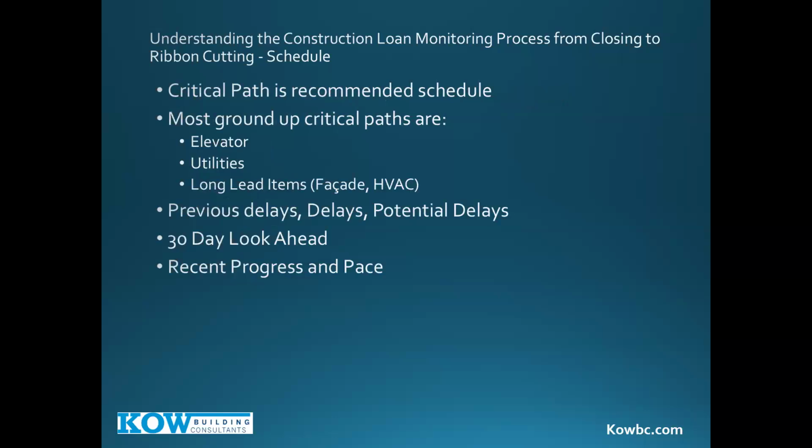And the critical path format is the recommended schedule. I'll give you a quick education on what critical path is if you don't know. The critical path is the longest period of time that's needed for project completion that you must go through in the right sequence. So a perfect example is this.